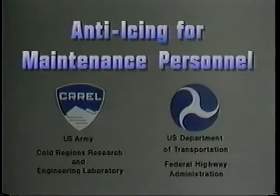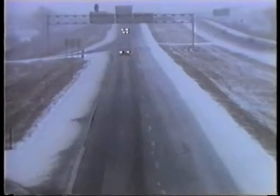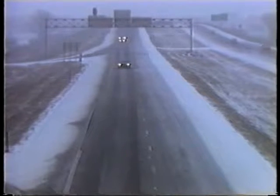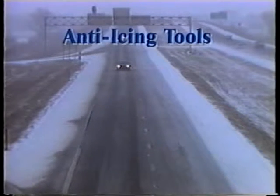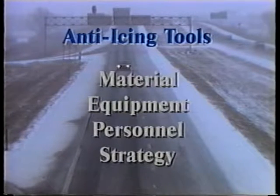The information presented here is intended to help maintenance managers and field personnel implement effective anti-icing programs. Further details can be found in the Federal Highway Administration publication, Manual of Practice for an Effective Anti-Icing Program. Anti-icing is a systematic approach to winter road maintenance that requires the use of the right tools, material, equipment, personnel, and strategy at the right place and at the right time to prevent or reduce the ice-pavement bond.